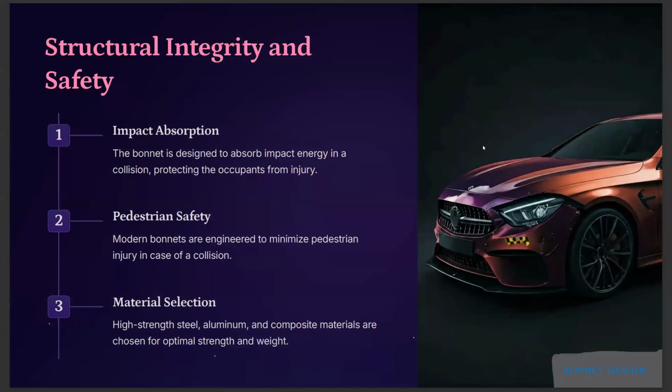Then after the forces, you have other considerations to take, that is your safety concerns. It can be any type of safety. It can be pedestrian safety, or vehicle safety if by chance there is a frontal impact. The forces have to be absorbed by the hood, the bonnet itself, before the force travels to the chassis, your A pillar.